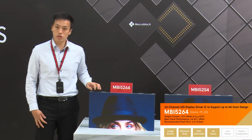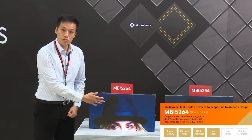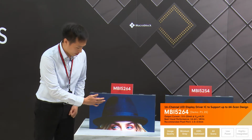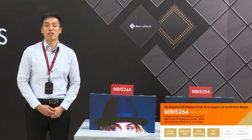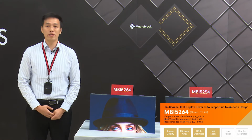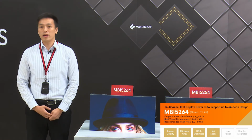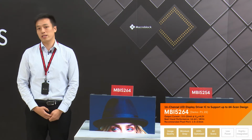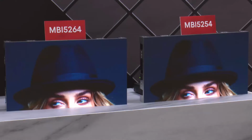Please stay closer and look at the detail of the picture. With MBI5264, the dark will be darker, the bright will be brighter. The main difference between MBI5254 and MBI5264 is that MBI5264 can support HDR-Optimized, 16-bit grayscale, 4K refresh rate, and over 20,000 contrast ratio.